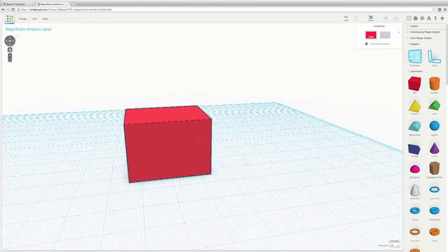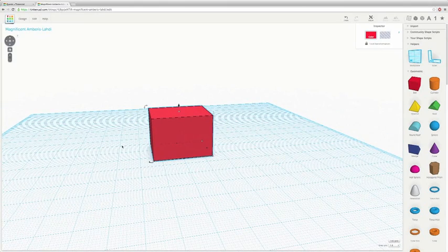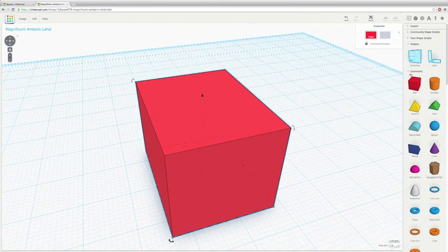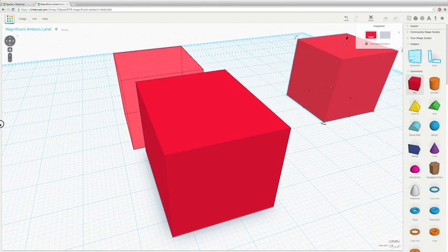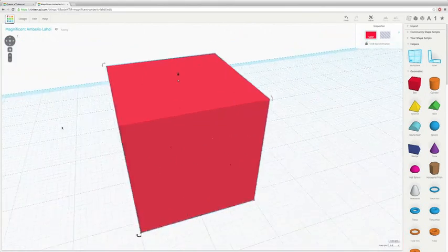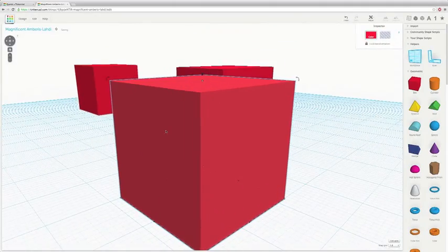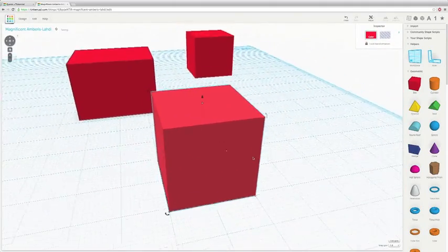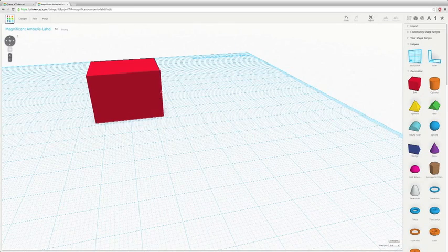It's much easier. When you have an object selected, you can hit F and it will focus onto the object. So if I had several different objects, I could select one, press F, focus on it, navigate around, select another, press F, and very quickly rotate between different objects.